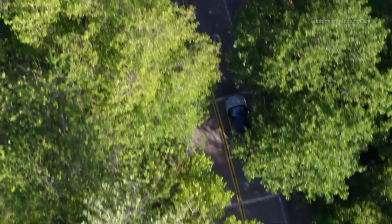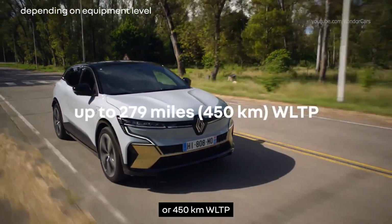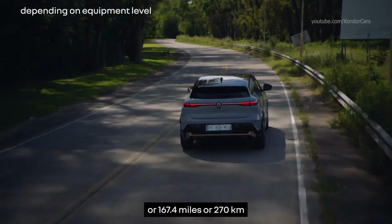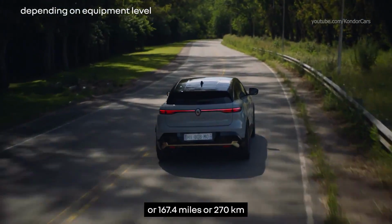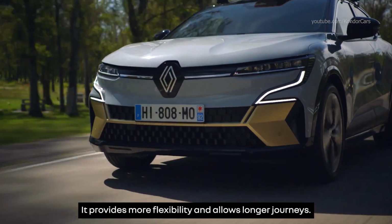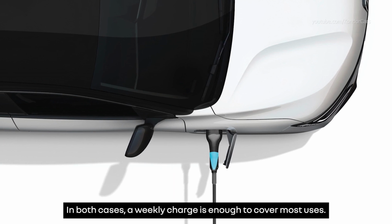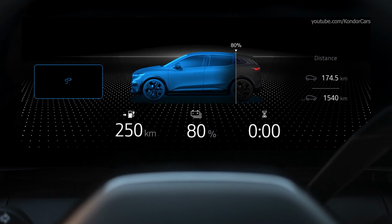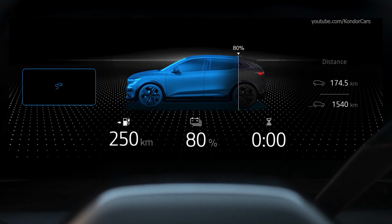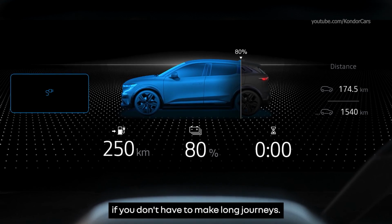route. The 60 kWh battery has a range of up to 270 miles or 450 kilometers WLTP, or 167.4 miles or 270 kilometers for motorway driving. It provides more flexibility and allows longer journeys. In both cases, a weekly charge is enough to cover most uses. You don't need to recharge your battery every day. A charge of just 80% is recommended if you don't have to make long journeys.